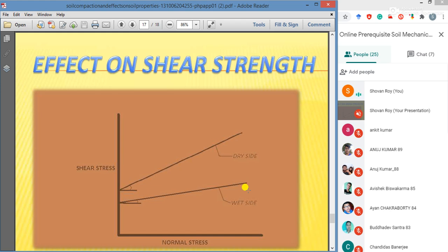Okay, maximum rain is going on in Cherrapunji, in the northeastern part of the country, where you have to construct your road, you have to construct such kind of earthen structure. Then what will you do at that time? This wet density is important to maintain, but the proper idea of the function of wet density is only possible when you perform all the lab tests, like